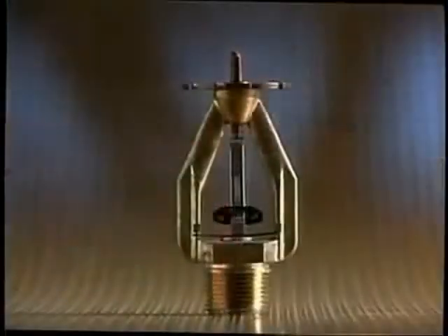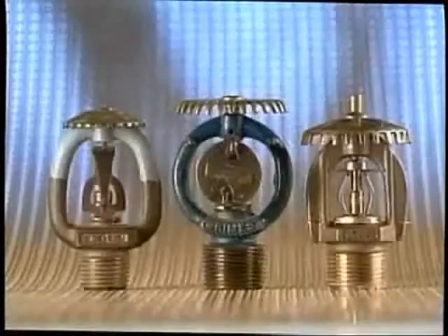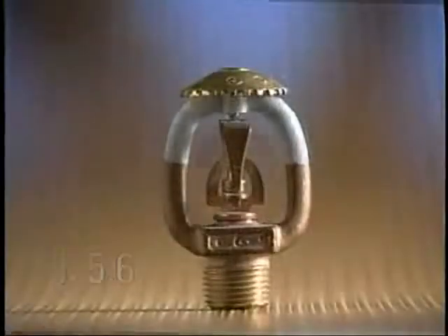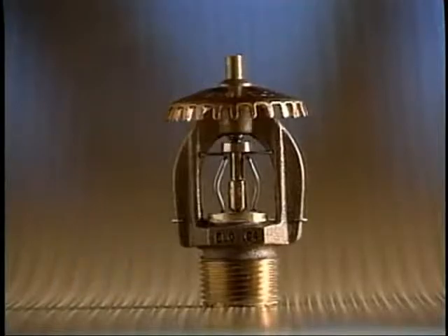We're going to take a look at these sprinkler protection options. We'll contrast and compare the ESFR, the large drop sprinkler, and the standard sprinklers, which include the 1/2 inch, 17/32 inch, and the ELO or extra large orifice sprinkler. There are many variables that go into developing a good protection scheme. Factors such as the type of commodity being protected, building construction, storage arrangement, storage height, ceiling clearance, aisle width, and many more contribute to the complex picture that helps shape each protection option.